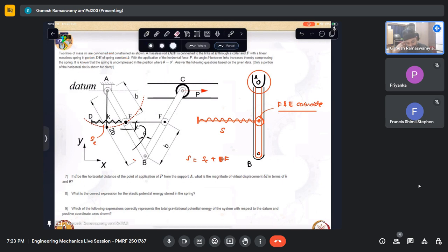Then you apply the energy principle in order to obtain the equilibrium of the system. What does the energy principle state? It is just a rewording of the principle of virtual work, which says that the virtual work done by all the active forces on a system is zero. So actually solving it by force, I will get one force here, 2mg will be there because two weights are there, and then kx, the force in the spring.